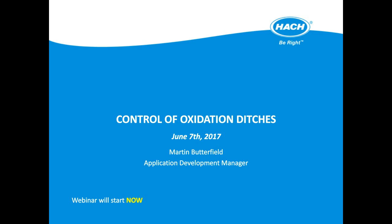In today's webinar, I'll cover a short history of oxidation ditches, their advantages and disadvantages, an outline on their design and possible modifications, their ability to nitrify and denitrify wastewater, and also alkalinity issues around nitrification in combination with the lower phosphorus consents that are coming in.